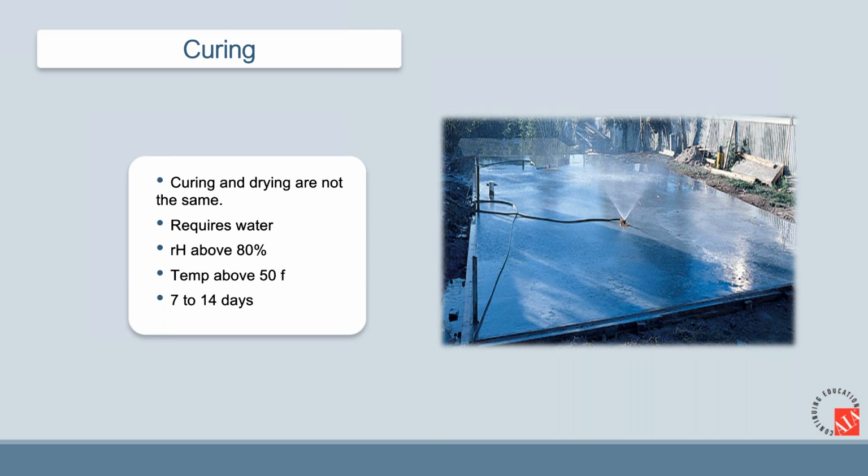What I mean by that is, if you look at the concept of curing and drying, they're not the same. As a matter of fact, it's really important to define curing in that it is not something that you can buy in a bucket. Curing is not a product. It is a process. Curing is literally defined as a one-way linear chemical reaction that takes place when you consolidate and bring together all of the different components that make up concrete.